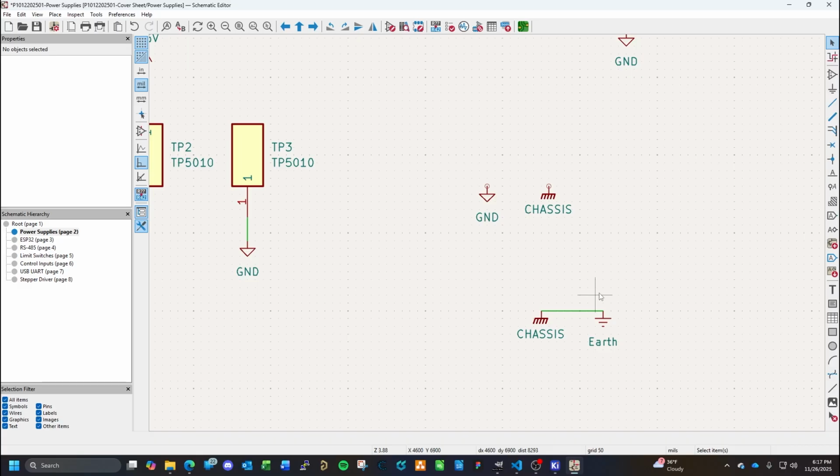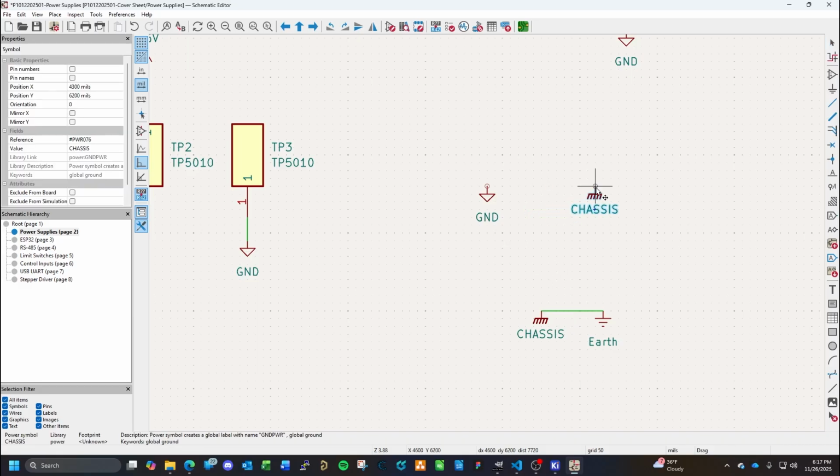You ensure that all the chassis components, like a door, access panel, anything that can be broken away and still hang on to the machine, have a good solid connection to the rest of the chassis and then to the earth ground itself. It's typical ground strapping. So if you're following proper design protocols, you would have your chassis ground and your signal ground.